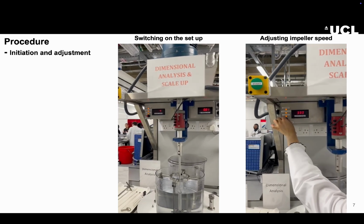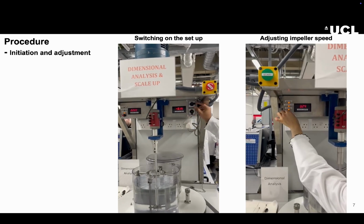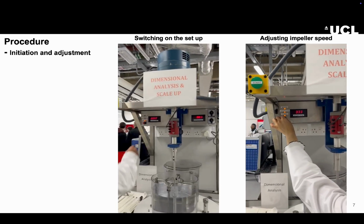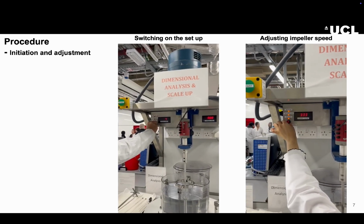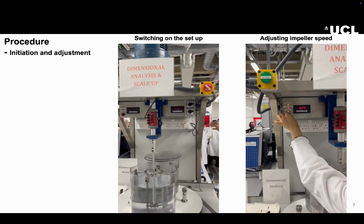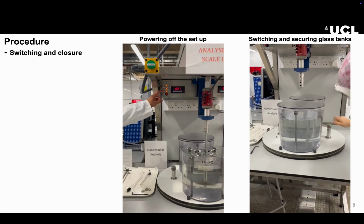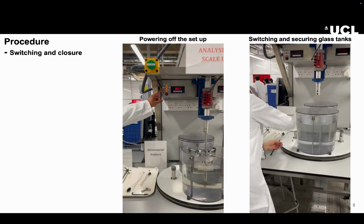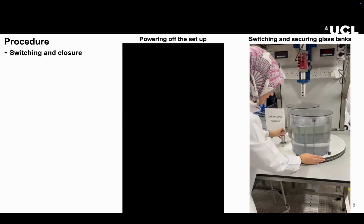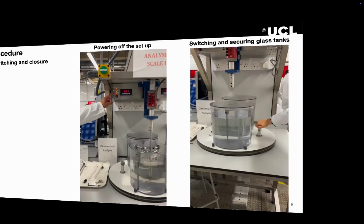The speed is incremented by 50 to 100 rpm, up to a maximum value of 650 rpm, and the torque measurements are repeated and recorded for each speed. The experiment is repeated using the larger 0.1 meter diameter impeller, and the torque values are recorded by varying the speed of the impeller. Once the experiment is complete, the system is powered off and the impeller is detached using an Allen key. The glass tanks are switched and secured, and the experiments are repeated with the 50% glycerol tank. Once all the experiments are complete, all the equipment is cleaned in the sink.